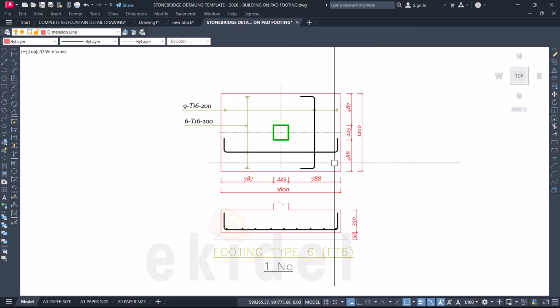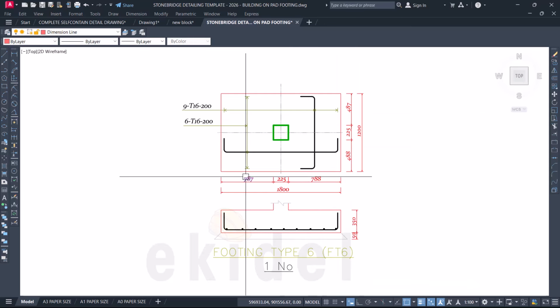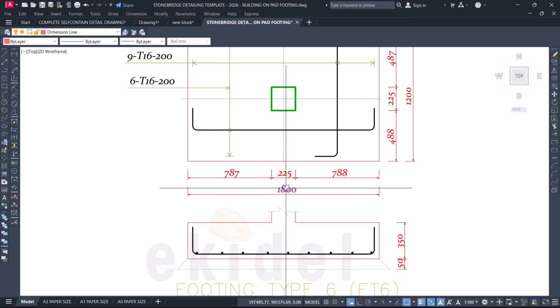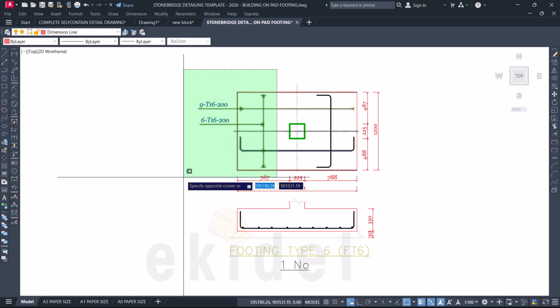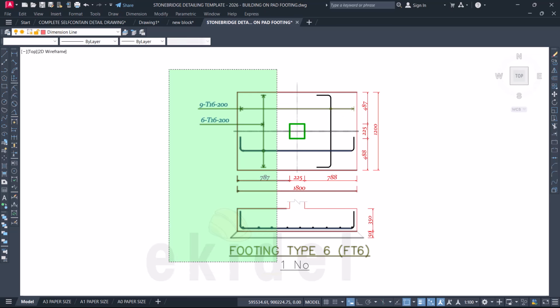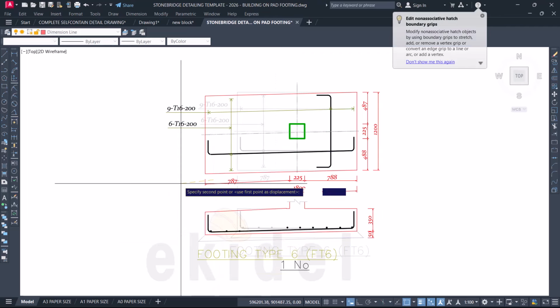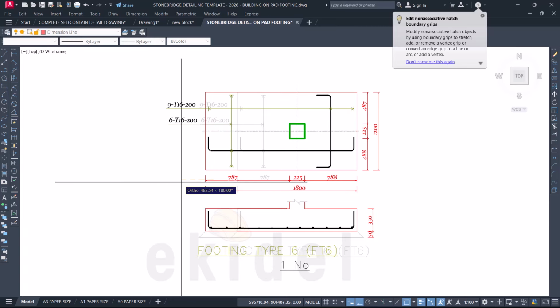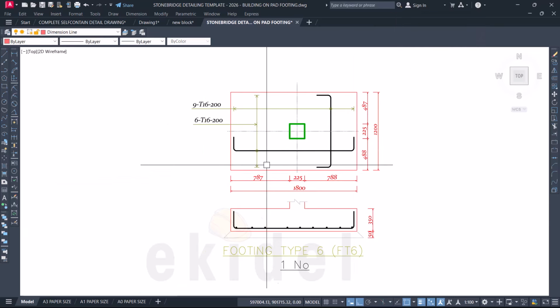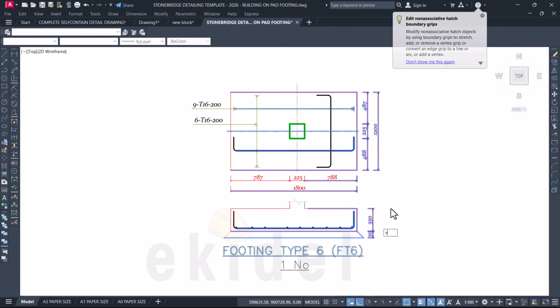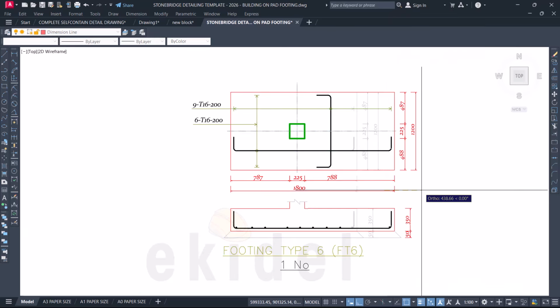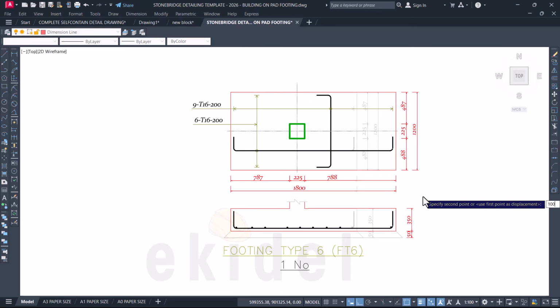So come now and modify this to, here is already the same 1200, but we modify here to be what? 2000 now. Here 2000. So we need to stretch 100. We make it to 2000. So we come now, come here, stretch this by 100. Click outside here. Make sure your auto is on. To keep the line straight, press 100, enter. Again, click here, click anywhere here. Make sure your auto is on. Sorry, that is stretch. Click here, type 100. Okay, that's fine.